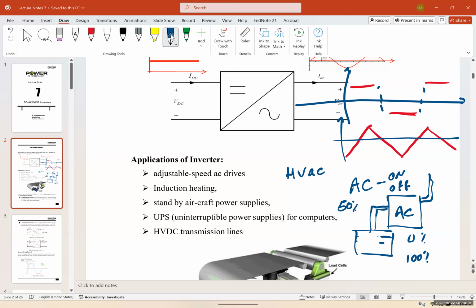It requires a lot of electronics, and the more important thing is DC motors. Usually they have brushes and commutators, especially the brush DC motors. I don't know if you're familiar with them, but they require maintenance. You have to change the brushes, and it's expensive. You have to service them every 4 or 5 years.